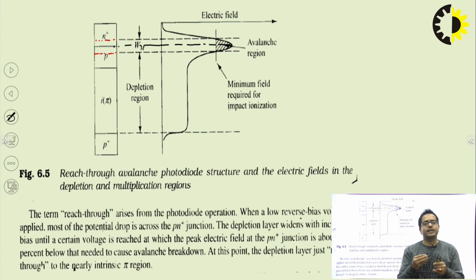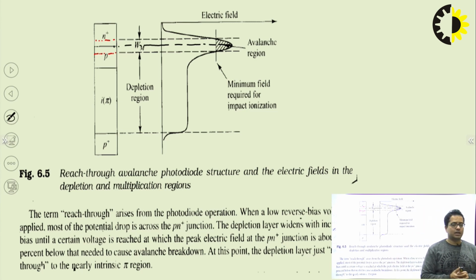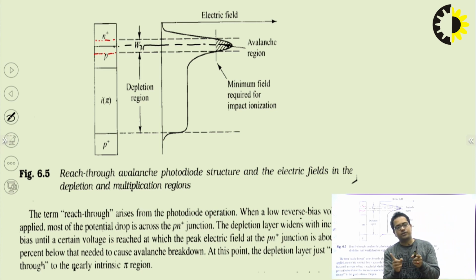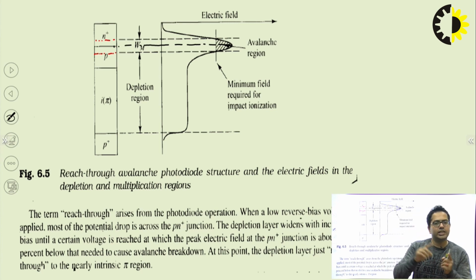Now there is another term, which is called impact ionization. In the presence of a high electric field, these electrons attain a very high velocity, and they impact another electron, hitting it with high velocity, breaking the bond of that charge carrier and letting the electron go free. These free electrons will start moving apart from each other with a very high velocity.